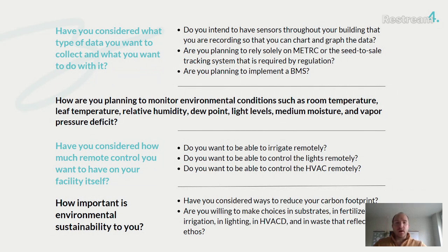I saw a great study that's still ongoing, I think it was last week, that showed that depending on exactly where you place just a temperature sensor, if you're in a shaded area or if you're directly under the light, you could have a 25 Fahrenheit degree difference from what the actual room temperature is versus what the temperature is that your sensor is feeding back to you. So making sure that you put those in the right placements, and of course, as more research is done, we're learning more and more where those placements are ideal.